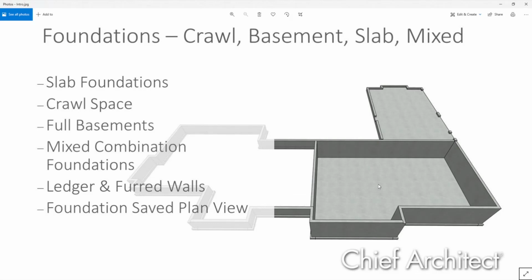Hi, in coastal South Carolina, we have a situation similar to Houston, but typically we do a 16 by 16 CMU filled column with a 24 by 24 footing, but we have to have a 12 by 12 continuous footing between the 24 by 24 footings. Is there a way to draw that? So you can make your footings any width you want. If I understand your question correctly, Charles, you have a certain wall that has a thicker footing or a wider footing.